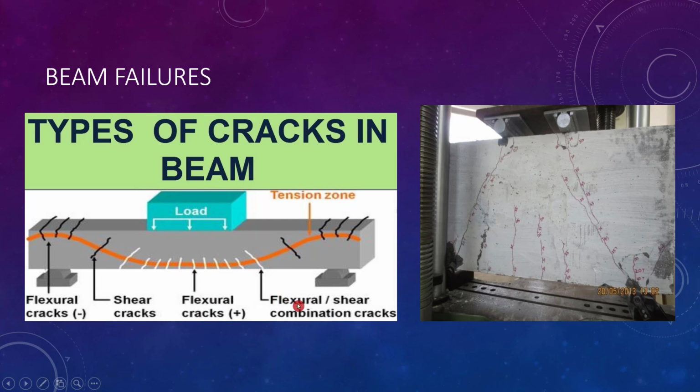and there also may be some combination of the flexural and the shear cracks, depending on the length and the design of the beams. So when you have a close look at these cracks, you can see that the flexural cracks are always normal to the length direction of the beam, and the shear cracks are always inclined. So this corresponds to the normal reinforced beams, and these beams will obey the simple bending theory.